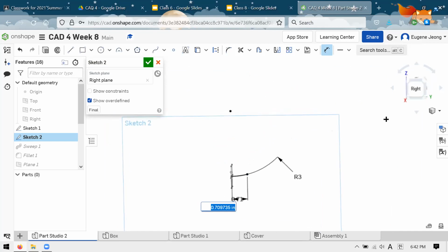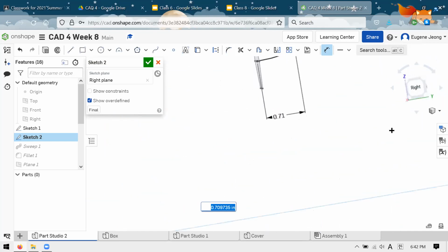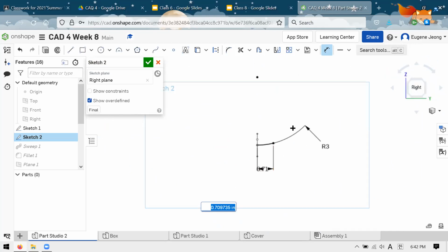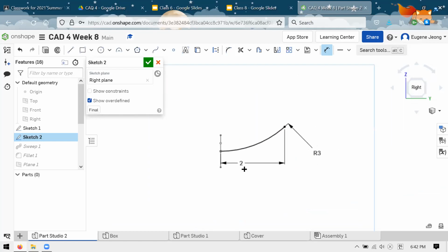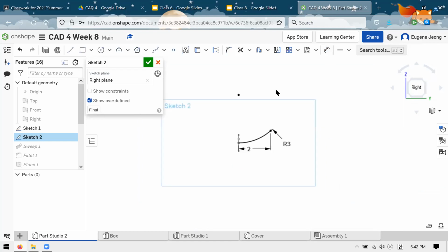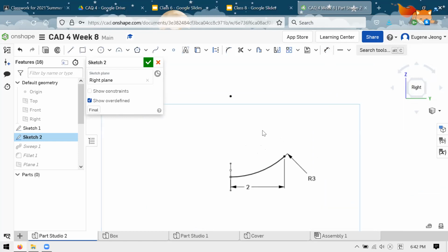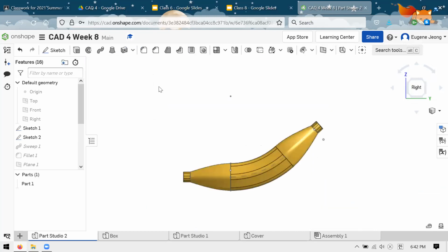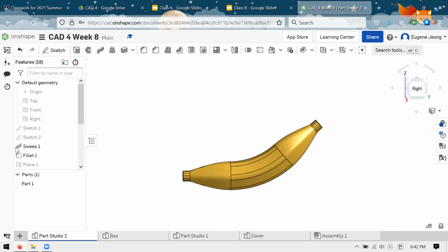Whenever you're dimensioning things, there are a lot of cases where there are two possible solutions, like we just saw. What you can usually do is get rid of the constraint and manually move it closer to your solution. Once you try again, it'll usually work. So hopefully that just updates the model and nothing breaks, everything's good.